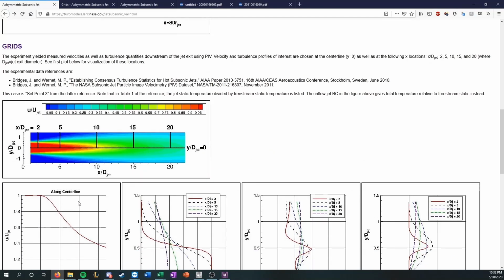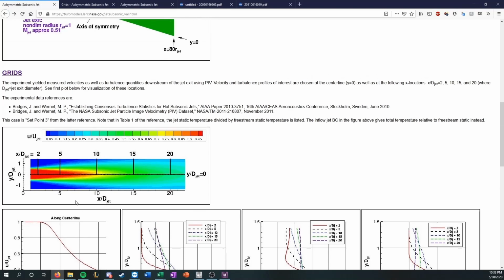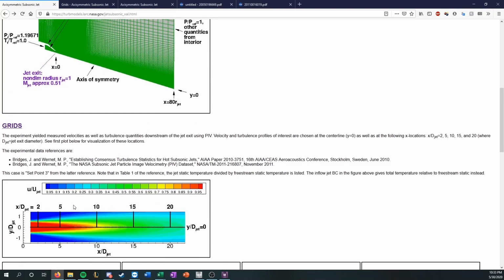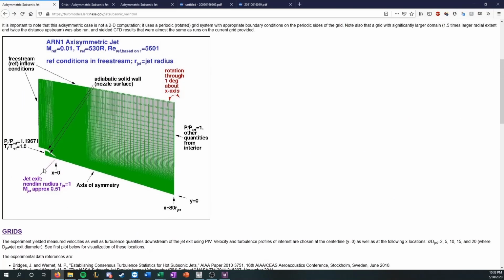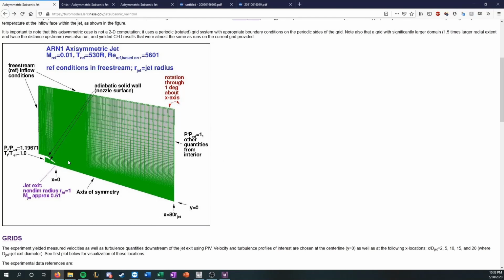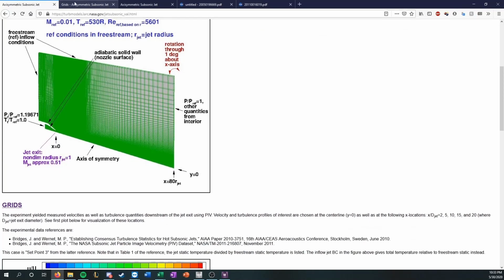And so getting started, the hardest part, the thing that I had to figure out first was where do I find the design of this grid? If you try to download this grid, it's almost impossible to use because it doesn't define the boundaries and it can only be imported into Fluent. You can use the grid if you use third-party grid software, maybe like Gambit or HyperWorks or HyperMesh, that would work. But for most Fluent users, the grid they provide is almost useless.